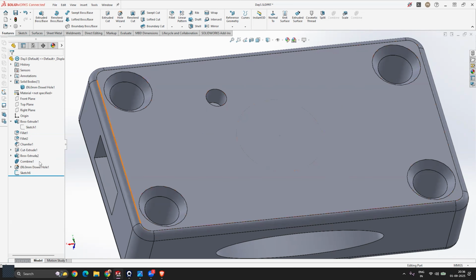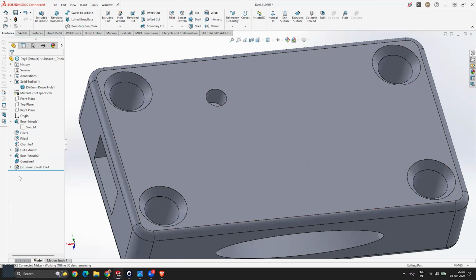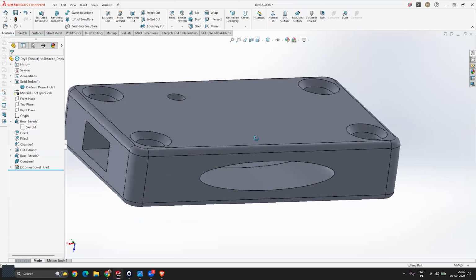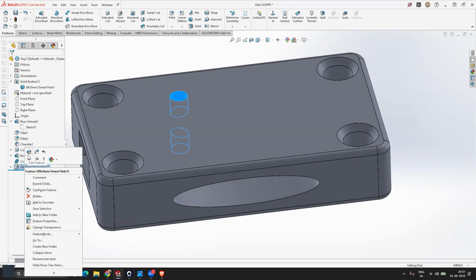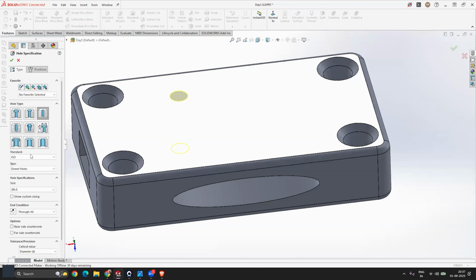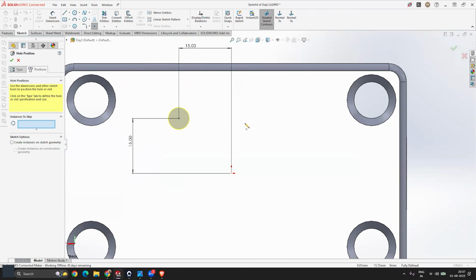And that way is, first delete this sketch 6 because we don't need this one. Simply select the sketch, press delete on your keyboard, press S, and that sketch got deleted, right? Yes, axis is an option, but there is another more optimized option that I want to show. So edit the whole tool that you did, go to the edit feature. Now go to the position tab.